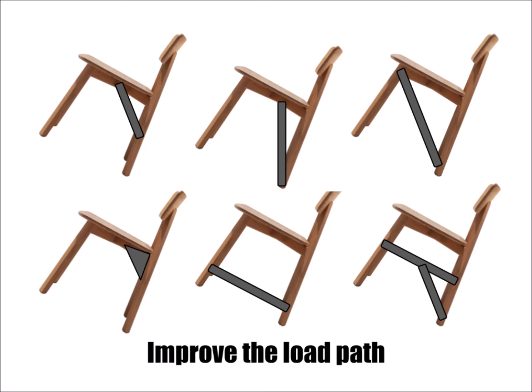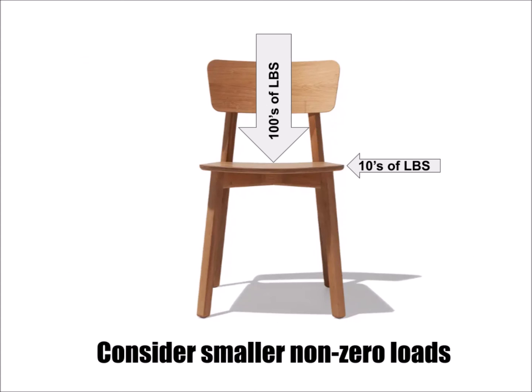Come up with various ways to reduce localized stress and minimize bending. In this case, maybe adding various braces or gussets could reduce the peak stress enough that the entire structure could be made lighter with the same load rating. In the real world, the loads are not ideal, and you can get racking, twisting, or off-axis loads that may be small in comparison to the main design load, but still need to be resolved.